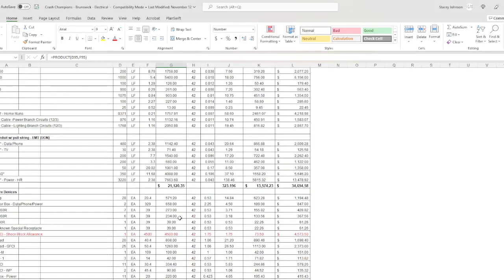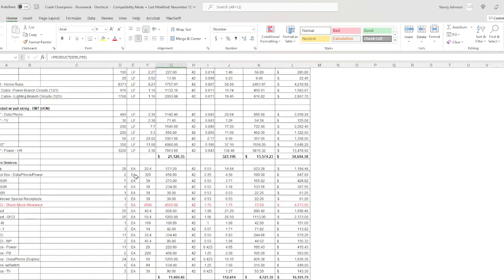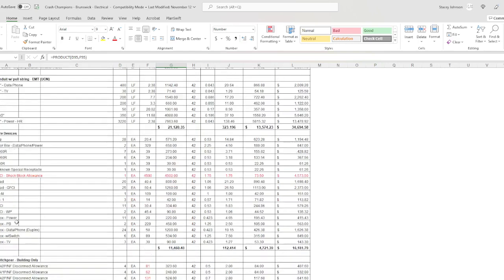So, all right. So counts. You got to make sure you have everything, all your wiring devices, everything from our power plan basically is on here. All your junction boxes for your TV outlets, for your phone outlets. Don't forget those. Plus, it's always going to say 3/4 inch conduit to the ceiling. So make sure you know how high the ceiling is. It could be 10 feet. It could be 16 feet. It could be 12 feet, whatever. So you want to make sure you have all that.